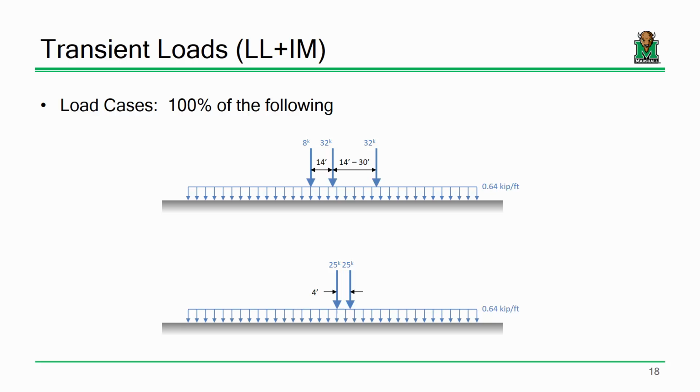So here's case 1 and 2. What's case 1? The truck and the lane. This 3-axle truck with the front axle being 8 kips, the two axles at the back being 32 kips. Variable axle spacing. We put the truck and the lane on the bridge, and try to get the maximum force response we can. I'm being a little vague with that because we're going to talk about how you do that very specifically soon. All right? Bottom, the tandem in the lane.